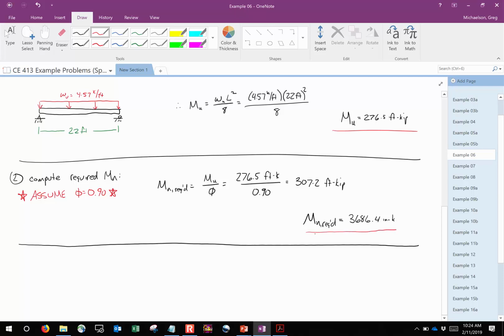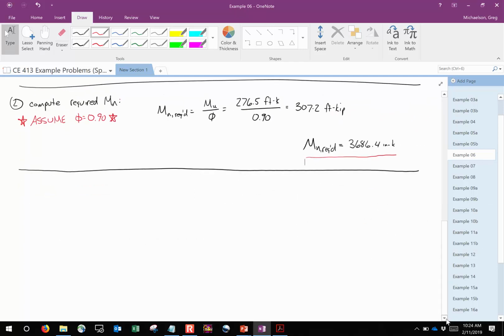Because what's going to happen is this, just so everybody's aware, at this stage in the problem, I'm not saying be fast and loose, but a decimal point here and there really isn't going to matter. Because what will happen is this, you'll end up calculating a required width of the beam, and let's say it's 15.8 inches. You're not going to size a beam 15.8, you're just going to round it up to 16. So you're going to round things up a bit, and then when it's all said and done, you're going to analyze the beam as is. So you got a little bit of wiggle room right now. Trust me, it'll be okay. Everybody good? All right, so what's step 3?